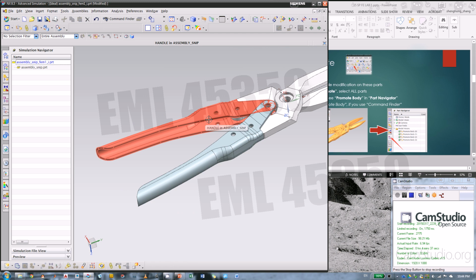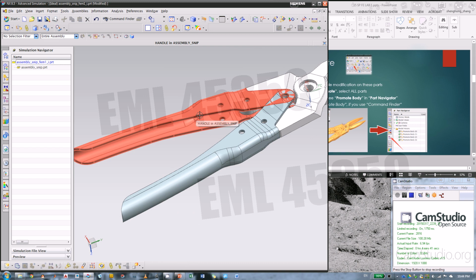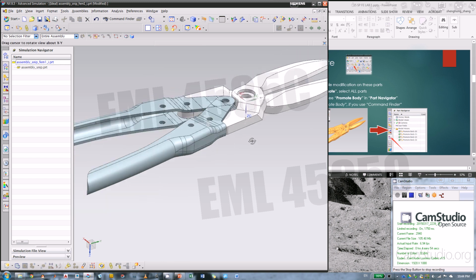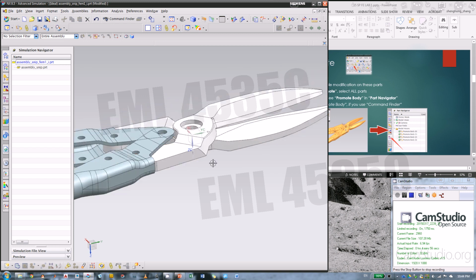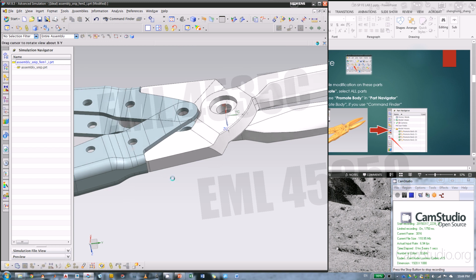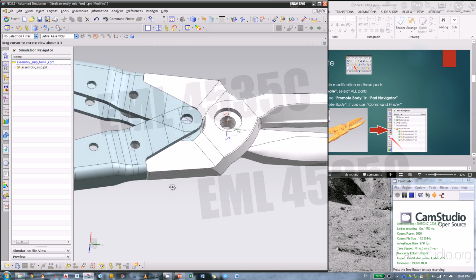So you want to use shell elements instead of just using tetra for everything. So those two are going to be shell, and we need to find the mid surface of the shell in this idealized part for the fan. And for the blades, this portion here is also a shell-like 2D structure.